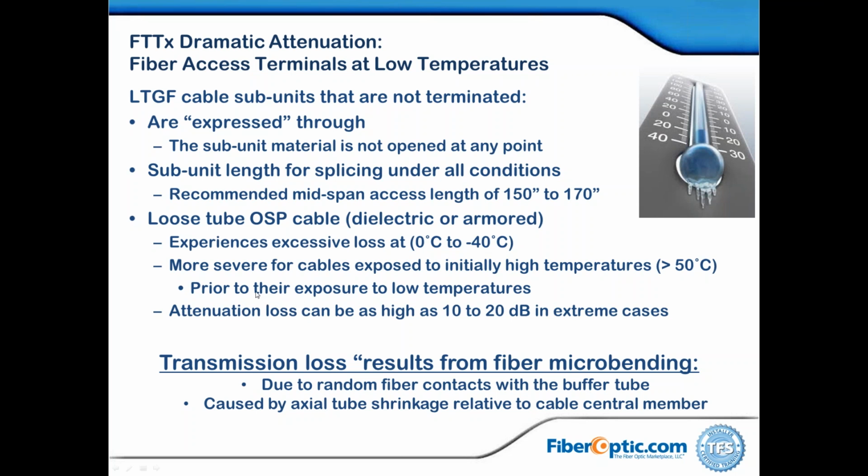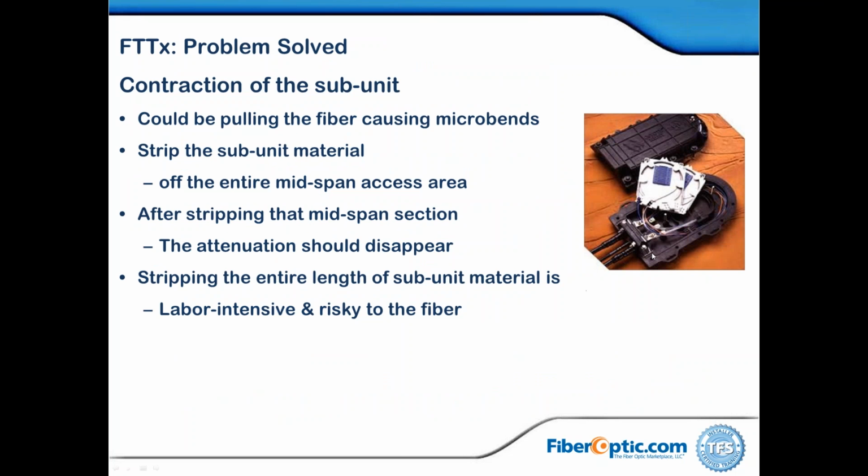Don't want to go too long, say certainly past an hour on this. But again, if you want to go back in, if you're in real cold environments, there are some things you might have to do resulting from transmission loss or microbends, how things are curved or how you put them in the splice tray. And that's about contraction of subunits, how you can adapt for extremely cold as far as expansion of the plastic buffer gel-filled tubes. You notice here you can strip all the buffer tube out of the splice closure, and then the individual fibers are free.